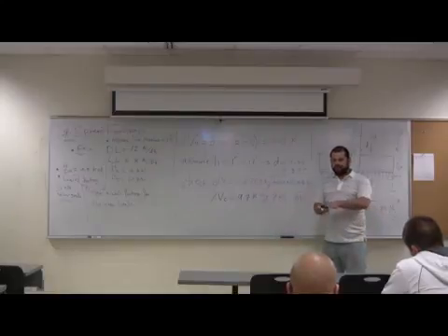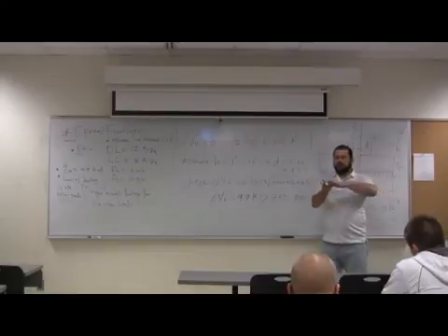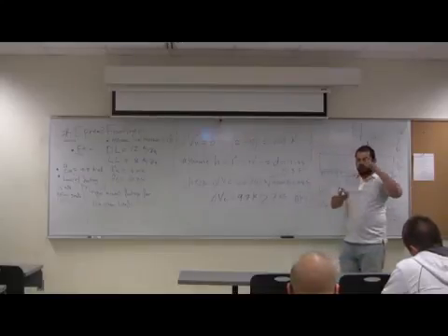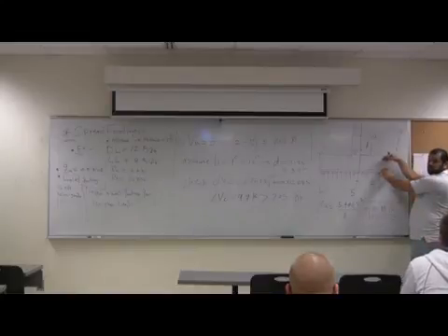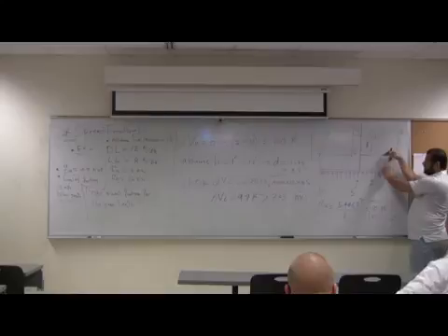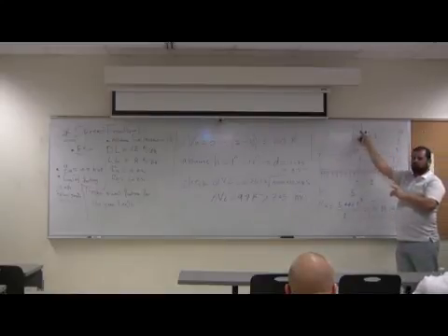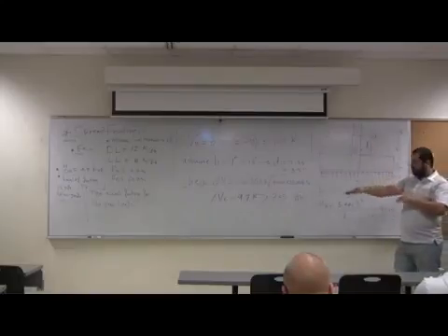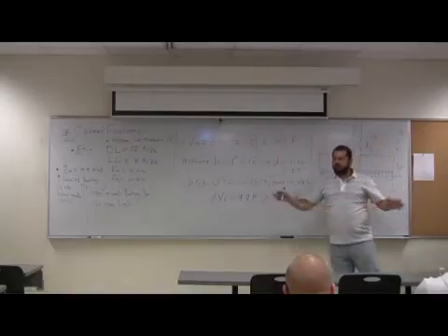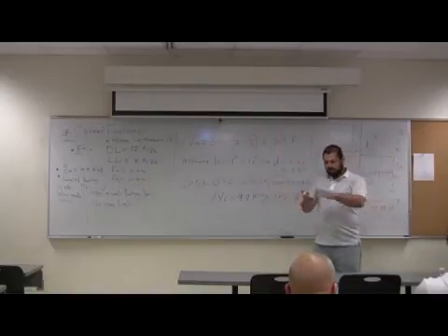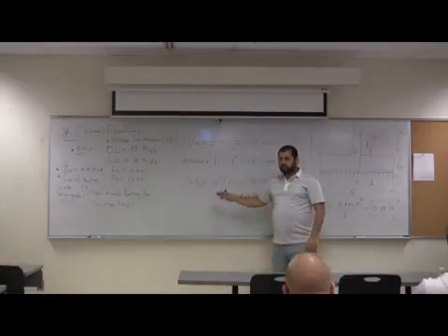That's fine. Remember, the footing in terms of concrete is not expensive. It doesn't need forming, so it's easy for the concrete thickness. And 10 is good to accommodate the covers. Remember, you need a cover of 3 inch from here and 3 inch from here, from the top, if there are bars on the top. Usually we have some bars too, so we can tie the wall rebars there. So you don't want to go less than 12 inch in any footing. Sometimes if it's really a minor wall just around the house to carry itself, you may go with 8 inch even. It's small.